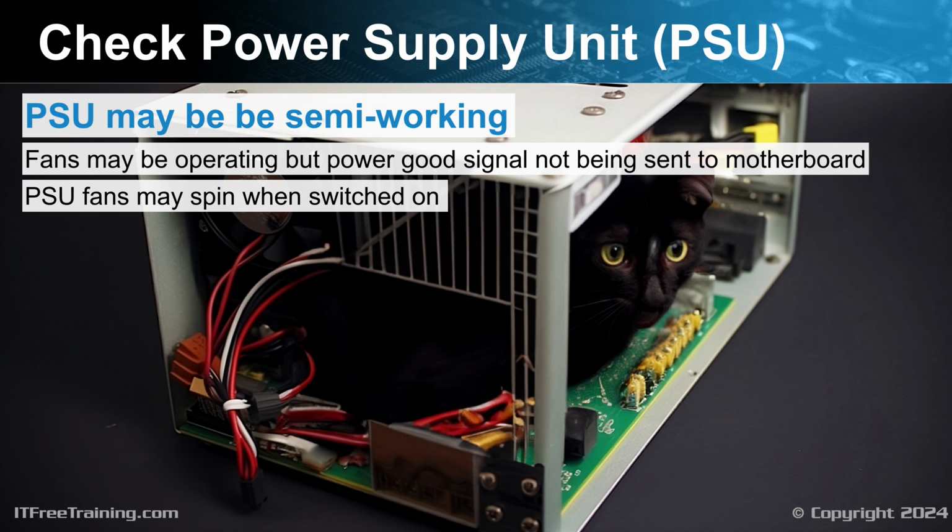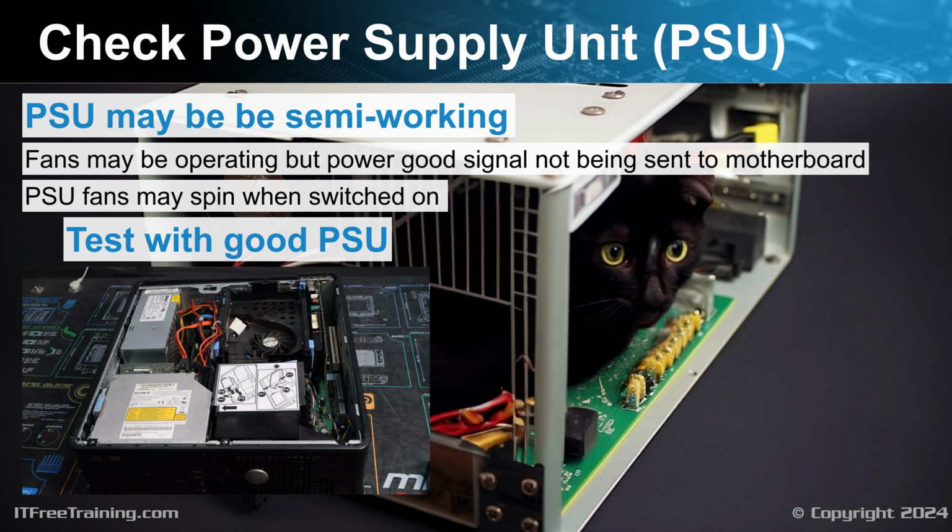Here the fans only start spinning when the unit requires cooling. Therefore, it is important not to make assumptions about power supply functionality without understanding the specific behaviors of your hardware. It is possible the computer is not starting up for other reasons. It could be the computer is not sending the signal to the power supply to start up, or the power button is broken or not connected. To test if this could be the case, you can test the computer with a known good power supply unit.